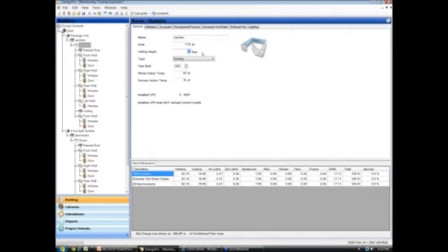If you've got sloped roofs, do an average ceiling height. This is going to change the volume of air inside the house. You need to be very careful when you're doing your wall areas, but this isn't going to automatically change wall areas. All this does is change the volume of air calculation inside the house.